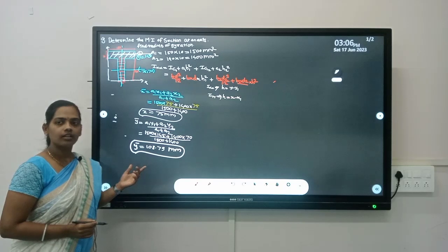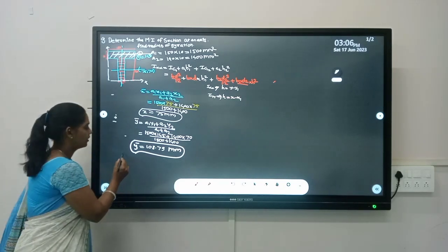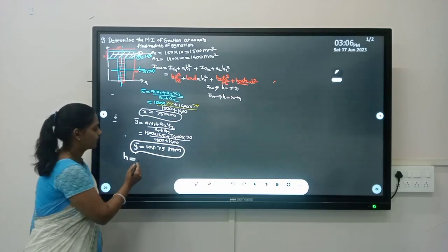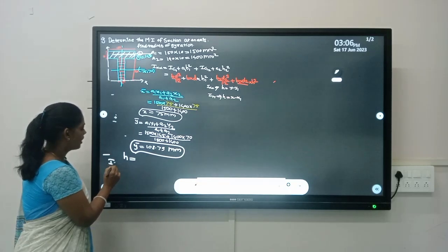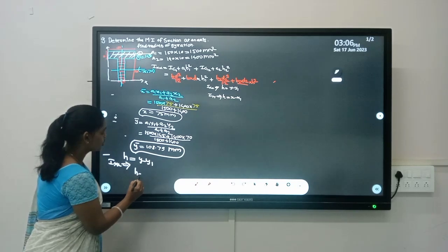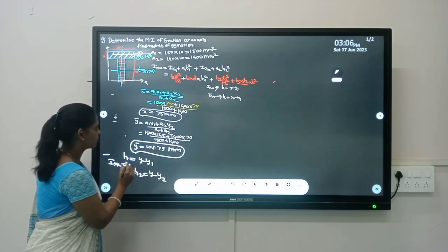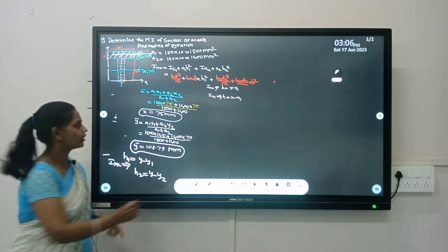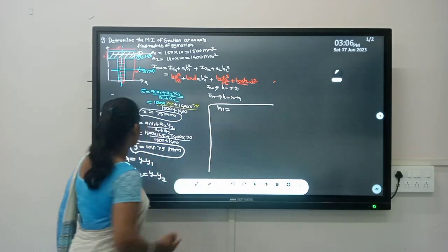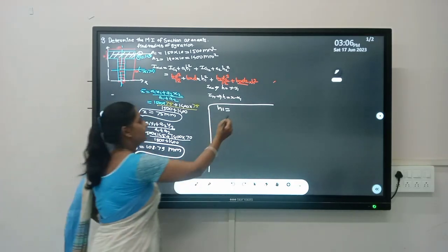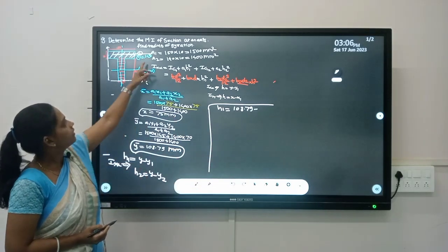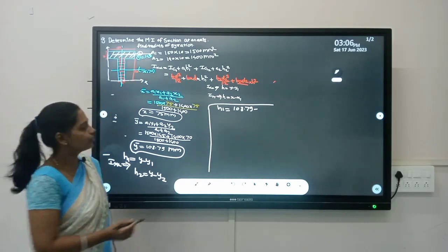Now we calculate, yes, what to calculate? Concerned height. Suppose h is equal to differences between, for Ixx, as we are concerned for Ixx, h is differences between y minus y1, and suppose h2 is equal to y minus y2. h1 is equal to y minus y1, h2 is equal to y minus y2. Therefore, h1 is equal to, what is the value of y? It is 108.79 minus y1, it is 145.